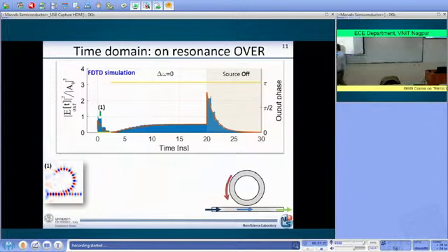Now if you look at the intensity of the light coming out as a function of time, the intensity starts to drop, because you are coupling more and more light into the microring resonator. This is what happens at the very initial instant of time.